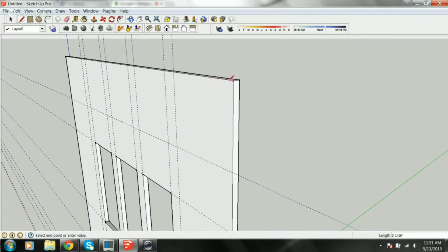Okay, so I've clicked on the top corner because this is the top of my parapet. I'm going to come out just for grins here, 18 inches, because I'm pretty sure that's beyond what I've got here for my parapet. I'm just creating a box to work with in the third plane. You see I was along the x-axis. I'm not going down. Okay, so now I'm going to go down on the blue axis, 36. I know my parapet's 36. And I'm going to come back. Green, it'll snap to. It'll typically always snap to red, green, and blue.